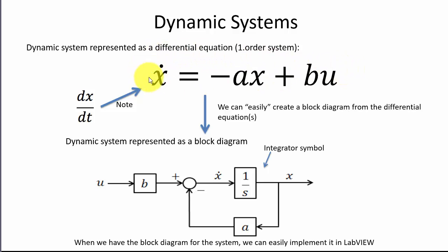So here we see a typical first order differential equation, and here you see the block diagram based on this equation. Here you have the integrator symbol, the feedback, and the control signal, and all these blocks are available inside LabVIEW. So this is the structure we are going to make when implementing the models inside LabVIEW.